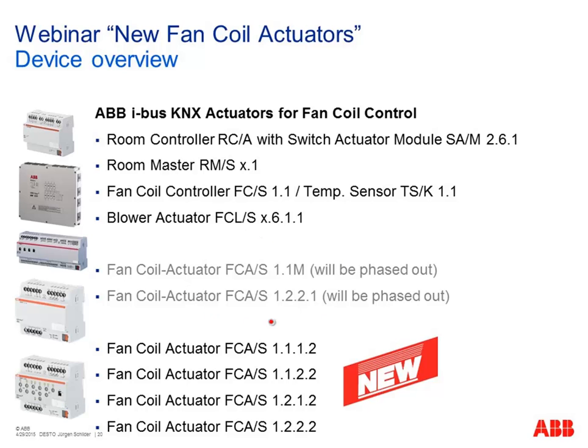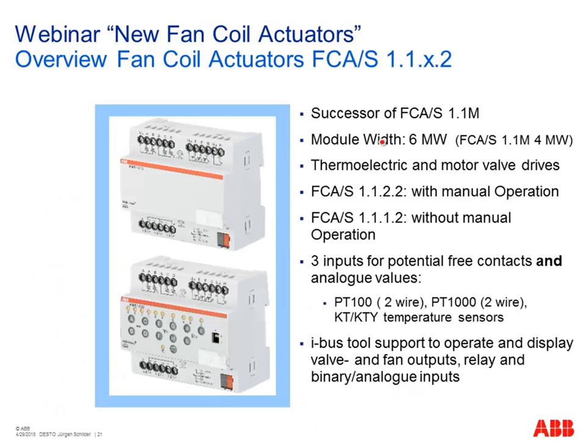Our existing complete fan coil actuators, FCA-S11M, for electrothermal valve drives and motor valve drives. And this version also existed for 0 to 10 volt valves, or more or less existed. These two devices will be replaced by 4 new components, shown here, and you will see what's behind. So the other one is still existing, this will be phased out, this is new. So let's have a look at the next 2 slides.